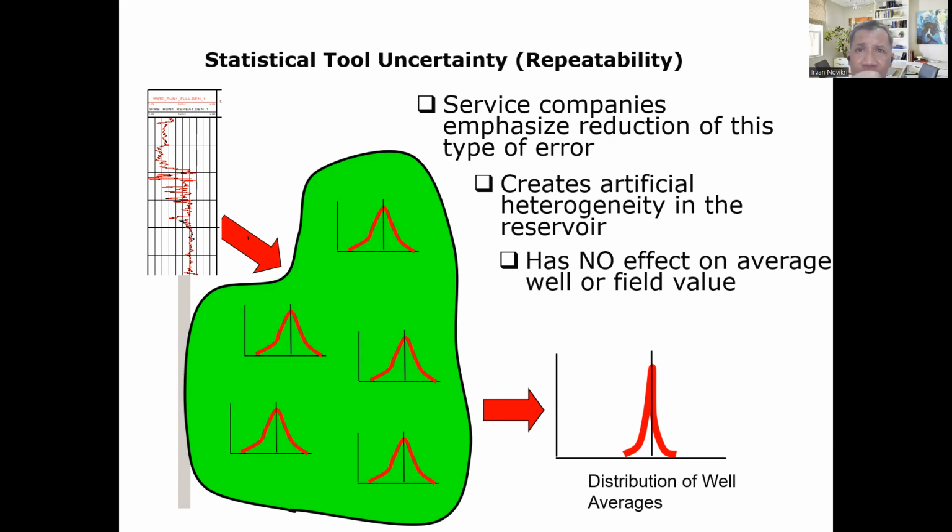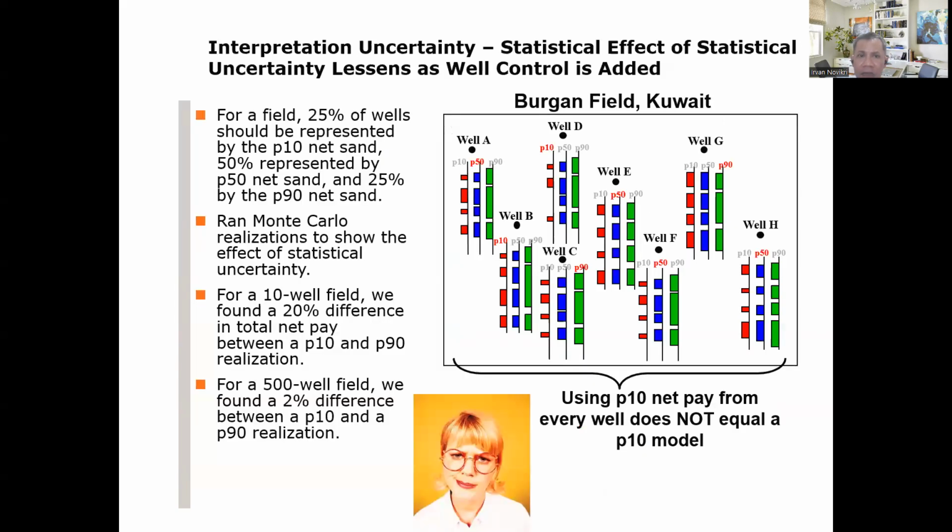In the context of measurement, again, accuracy is how close the measured value is to the true value, while precision is the consistency and repeatability of measurement. This happens with random error, fluctuation or noise in measurement, which can be reduced by averaging repeated measurements. On the other hand, systematic error causes inconsistency between measured and true values. Repeated measurements converge toward the systematic error, affecting the measurement accuracy.